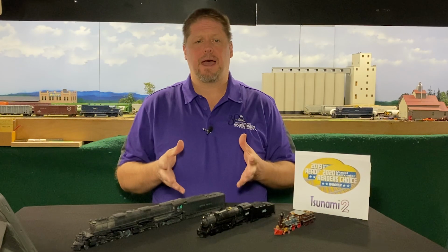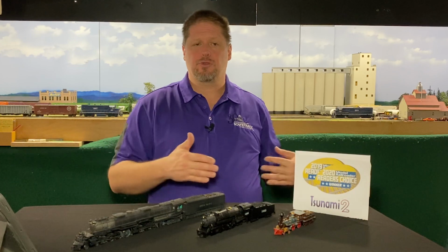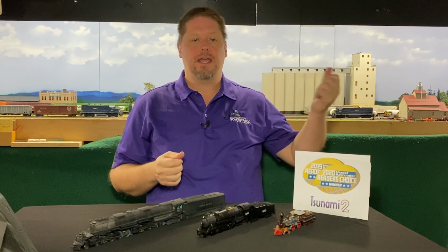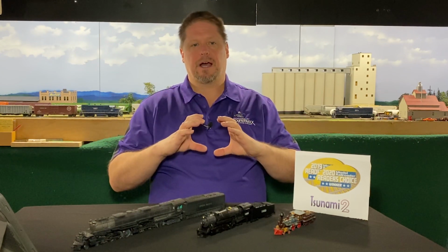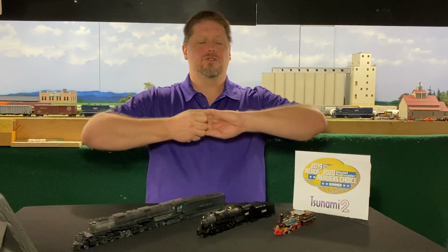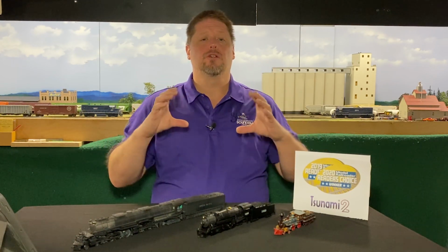You also have what's called the automatic, and the automatic brake ties into the train down the rest of the train and distributes that braking effort throughout the entire train, and that's the air hose that you see coupled between all the cars. Now, when the engineer wants to make a brake, the automatic part of this is he reduces the brake pressure in that line, and the brakes then will apply to the car. Part of the reason it's designed this way is, let's say, for example, down the line, one of the hoses breaks, comes uncoupled, or catches on something and tears. That air pressure line, if it's relying on positive air pressure to set the brakes, now there's no control of the brakes, and those cars are basically not going to be helping out in the braking effort. So the automatic brake relies on a reduction of pressure. Now, SoundTraxx Tsunami2 is able to reproduce both.